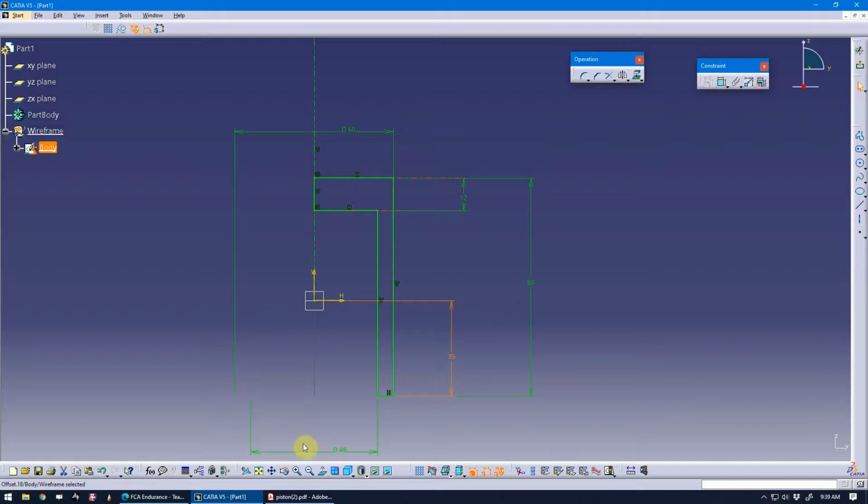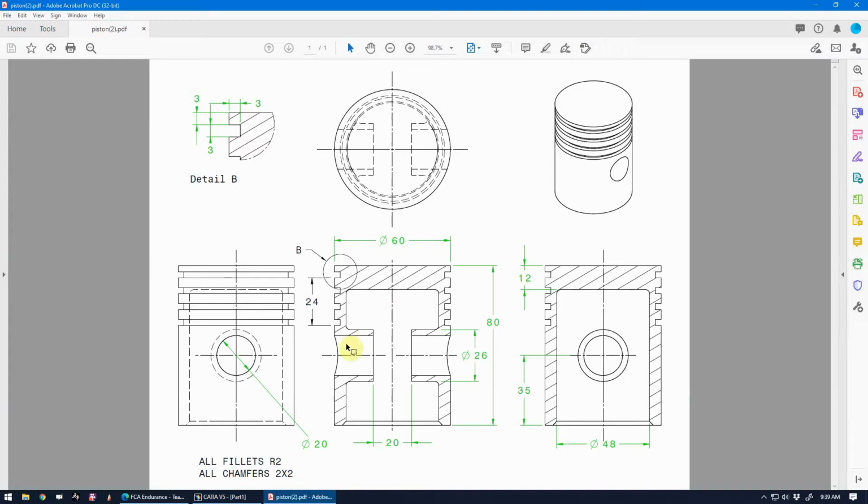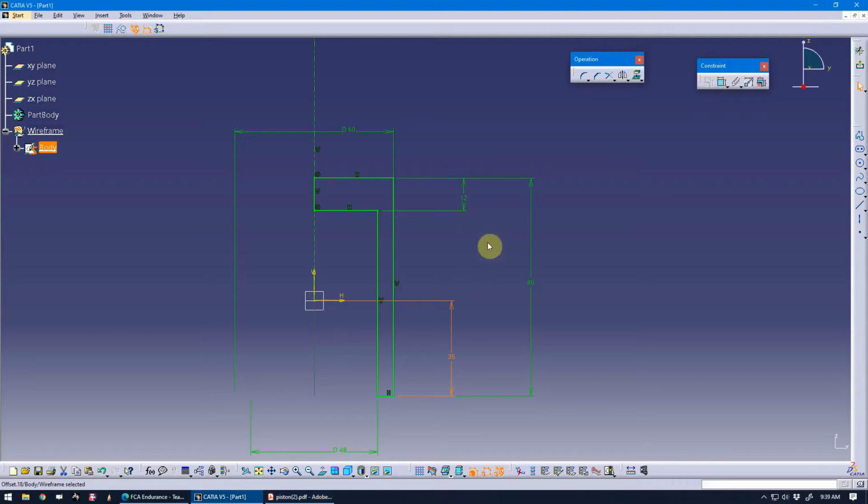And this is where the hole for the piston that connects to the connecting rod and the pin would go through this hole. So essentially the center of my working world is going to be right here in the center of the part. That's just my modeling strategy, because I'm thinking ahead about how this piston is going to go into an assembly model later. And so I find it might be easier if I put these default reference planes right here. So again, a modeling strategy.